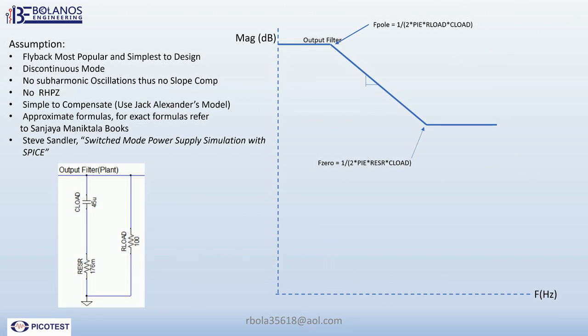Here are my assumptions. In this case, I've designed a flyback, and the flyback is the most popular and also the simplest to design type of switch mode power supply. I'm using discontinuous mode, and the reason is that it simplifies the design by not having subharmonic oscillations.